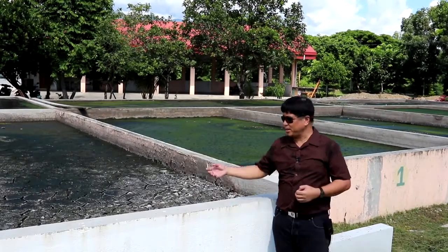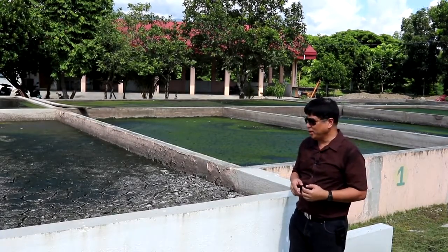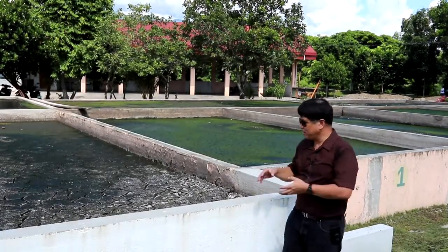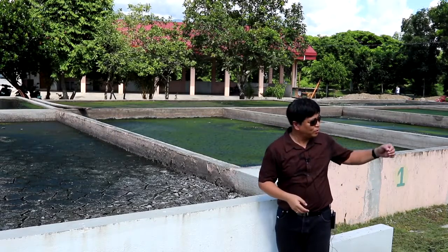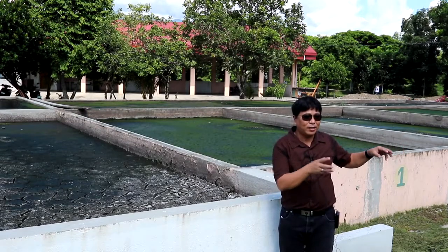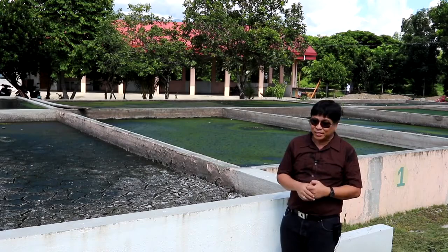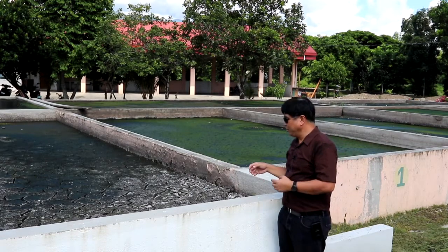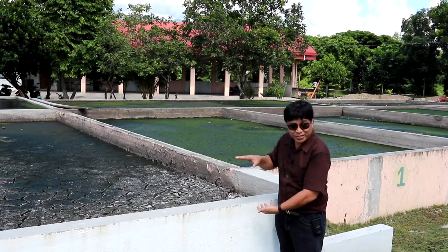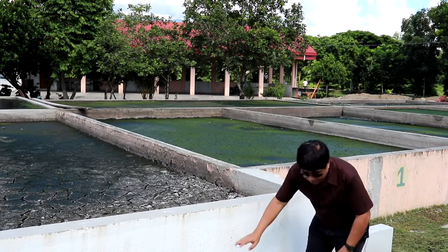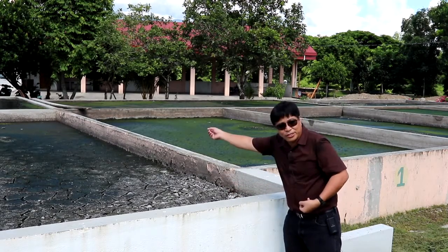At my back is the sludge drying bed, we call it. This receives the sludge deposited from the anaerobic pond, as well as some of the grit and sand that was taken out from the receiving area. As you can see, this tank consists of layers of gravel and sand. Down at the bottom, there's a perforated underdrain running across the middle.